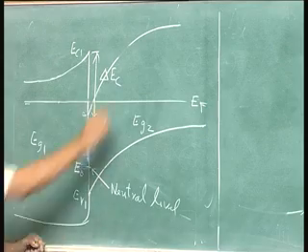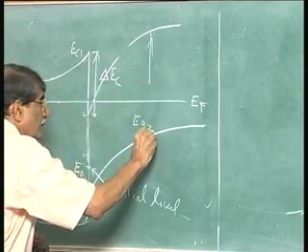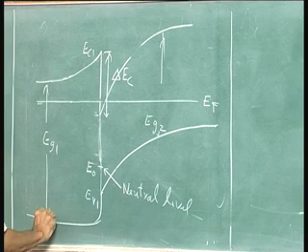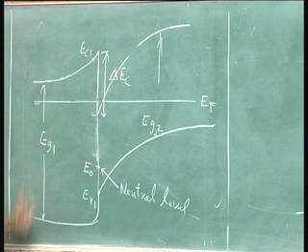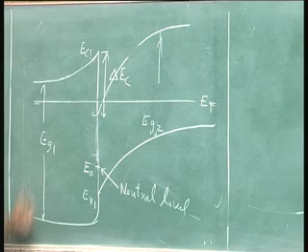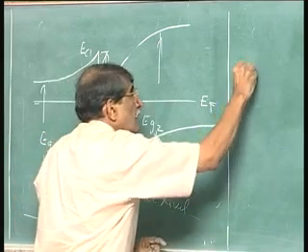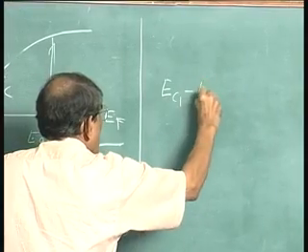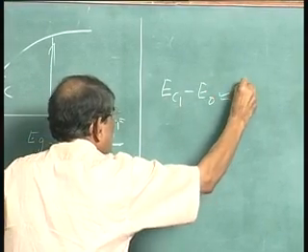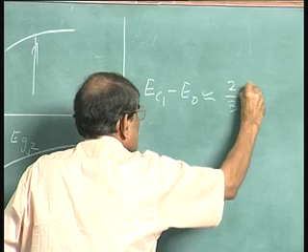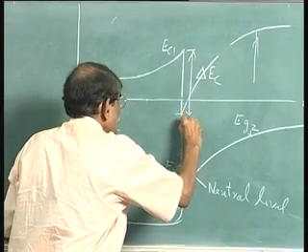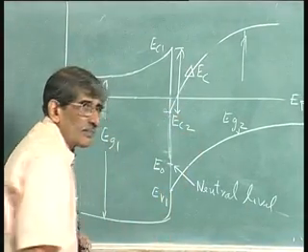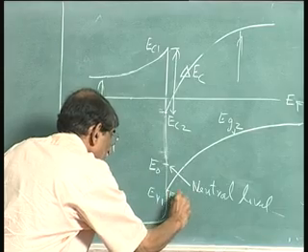This workout of course is not mentioned in publications somehow, but it is mentioned that the neutral levels tend to align, then you can work this out. So, if you know the neutral, okay, delta E_c is equal to E_c1 minus E_c2, that is actually equal to 2/3 of E_g1 minus E_g2, which is 0.66 times delta E_g.